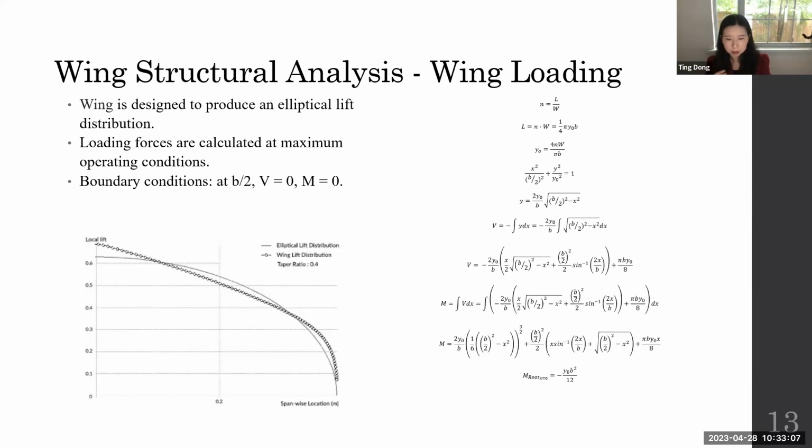So the thing we design is, let's say, the thickness of the spar or anything, and we have the stress, the maximum stress in your design, and the yield strength or allowable strength of the material we use, and then you have the safety factor. So normally this is the regular way we do the structure analysis: in the end comparing the maximum stress in the structure and the allowable stress of the material, and we know the safety factor, and we know how safe your design is.